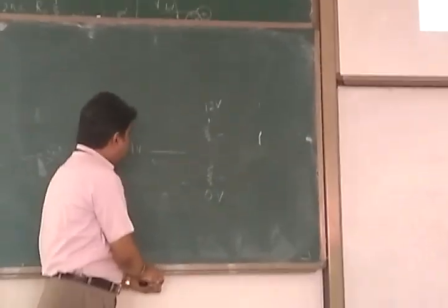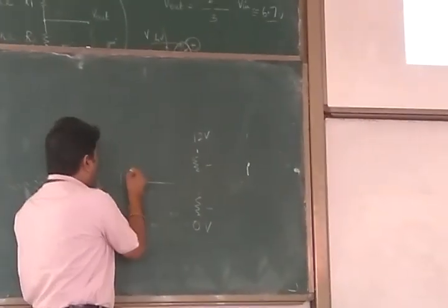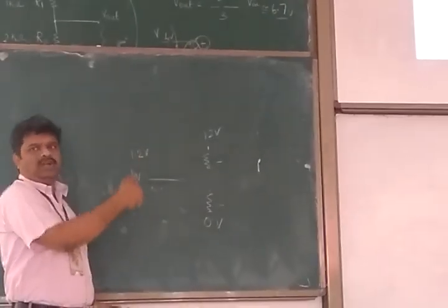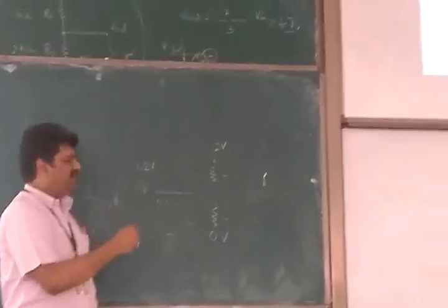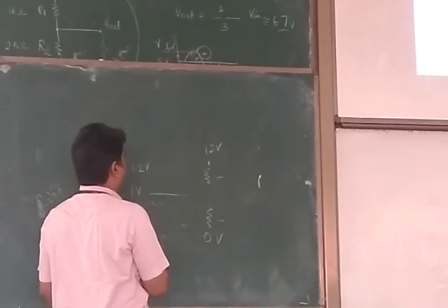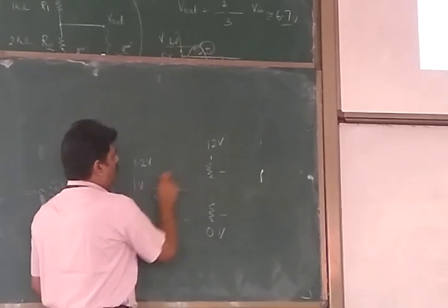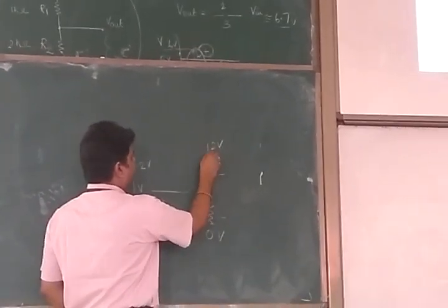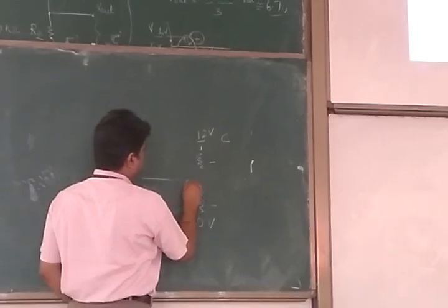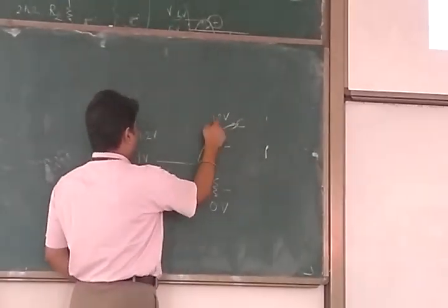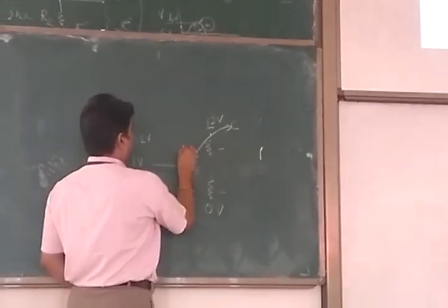Okay. Now look at this. When this voltage becomes 1.2 volt, because it can go up and down. It's a time varying signal, that input that we are giving. When it is 1 volt, what is the voltage difference between collector and base? 11. 12 minus 1, 11 volts.